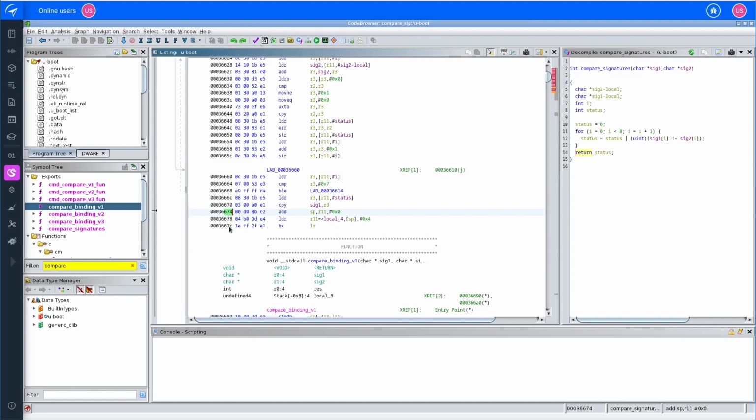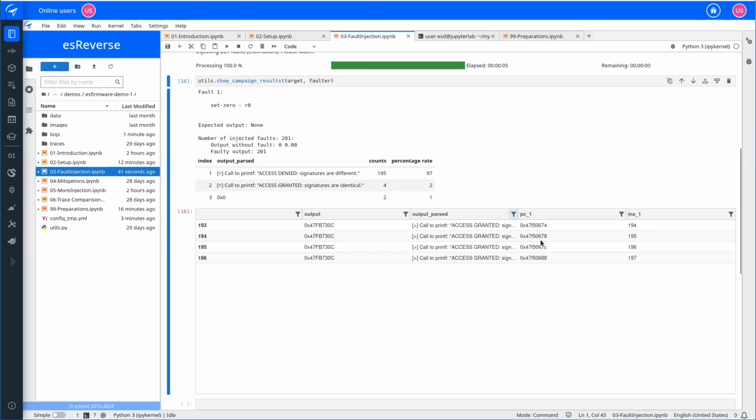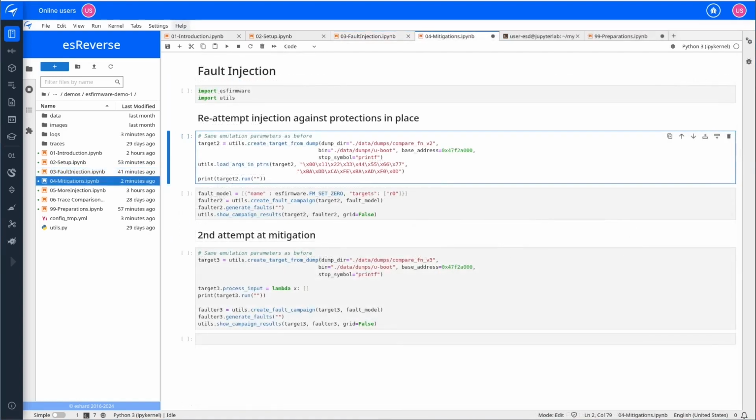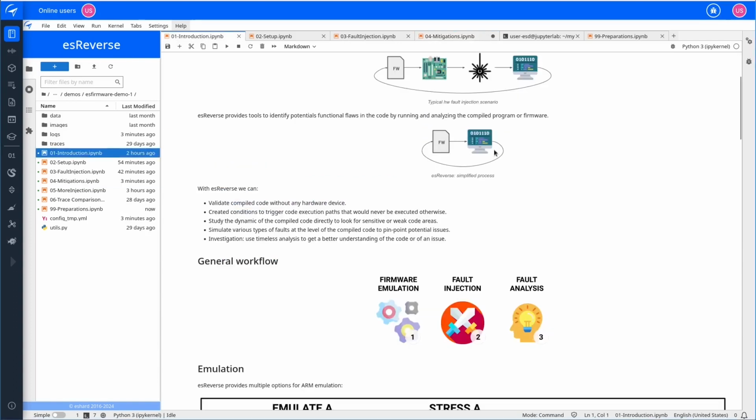Yeah. So we have 74, 78, probably 7C, and further. Okay, so that makes a lot of sense, and we are able to check what's going on there. Okay, now we've successfully asserted that our code contains a vulnerability against certain types of fault injection. So that was great, but now the fun begins because we can leverage that information and try to implement a mitigation against that. We are in this loop here that we saw before, where the developer gains some information and can loop back to its source code and try to implement something, try to make things better.